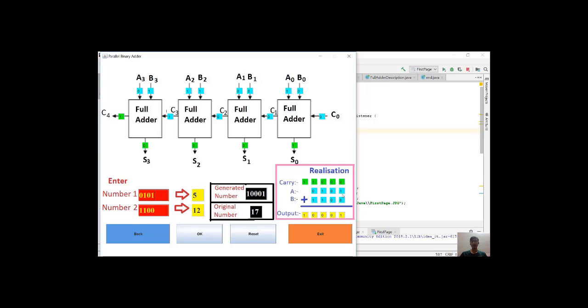1 plus 0, firstly the carry is 0, so we have taken default carry as 0. So 1 plus 0 is equal to 1 in binary. Then 0 plus 0 is 0 because no carry is produced, so here 0 carry is obtained. Therefore 0 plus 0 plus 0, the answer is 0. Here also no carry is produced, so here comes 0.